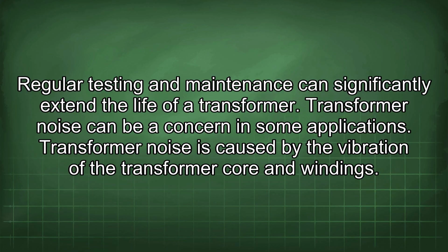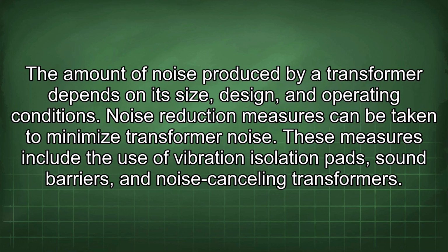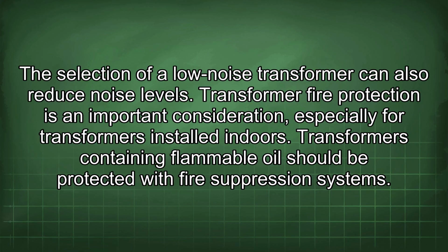Transformer noise can be a concern in some applications. Transformer noise is caused by the vibration of the transformer core and windings. The amount of noise produced by a transformer depends on its size, design, and operating conditions. Noise reduction measures can be taken to minimize transformer noise. These measures include the use of vibration isolation pads, sound barriers, and noise-canceling transformers. The selection of a low-noise transformer can also reduce noise levels.